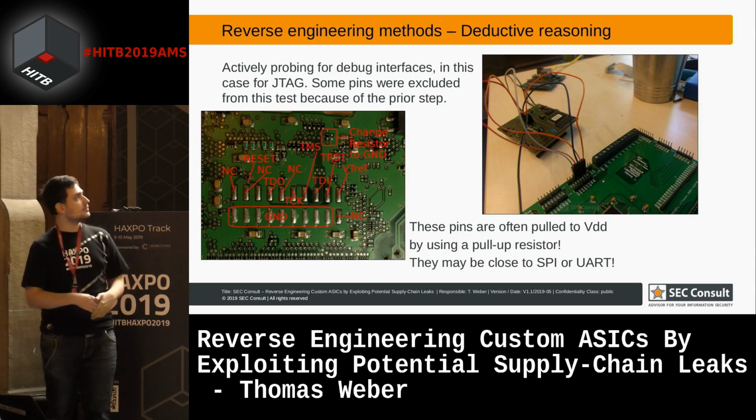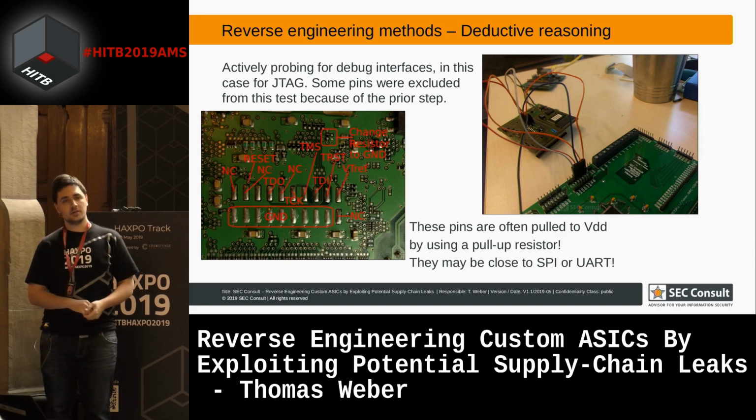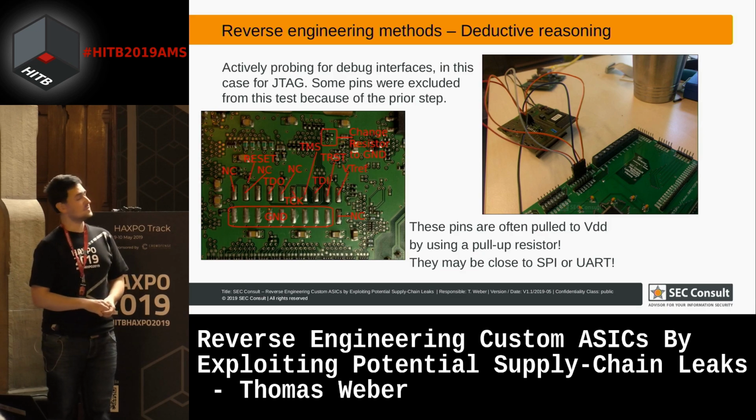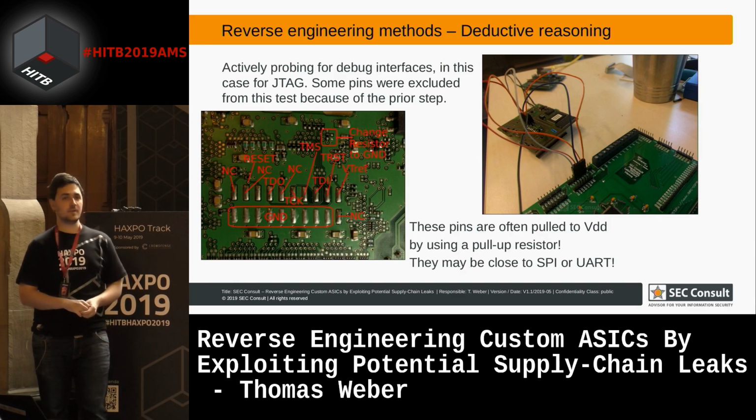And yeah, after connecting my device, the device what I have here, you can look at it afterwards. I got this pinout, and I attached a debugger and was curious because nothing worked. So I thought, okay, sometimes there are some activating, deactivating pins. When you pull it high, it is activated. When you pull it low, it's deactivated, or vice versa.